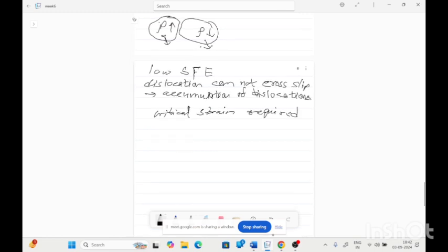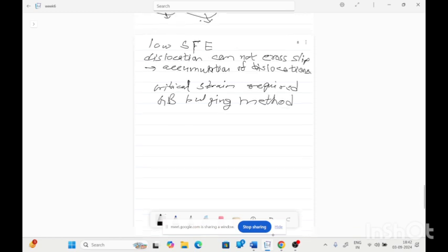The grain growth first is the nucleation of a strain-free region, then the strain-free region grows by the grain boundary bulging method. Serrations are also formed due to the accumulation of dislocations in this process.